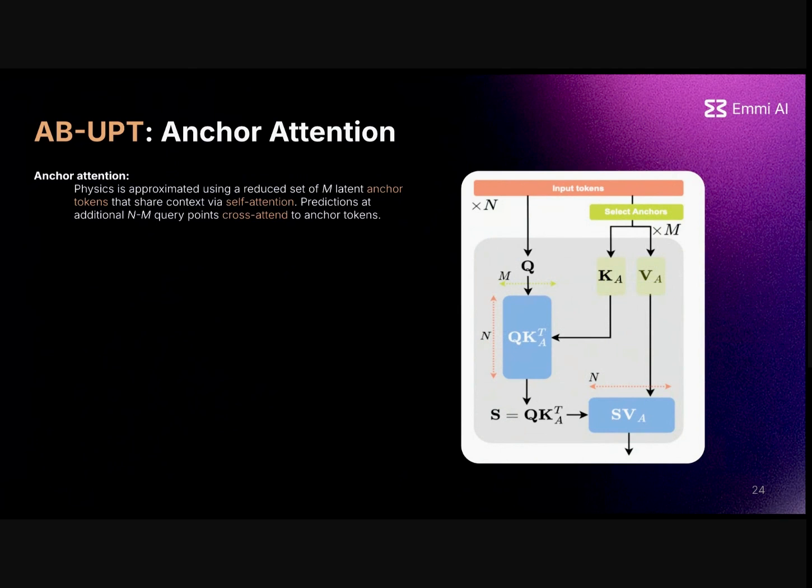But our model, as you just have seen, relies heavily on the transformer architecture and therefore on the self-attention block, which has a quadratic compute and memory complexity given the number of input points or input tokens. And if we want to scale to simulation-size meshes like DriveNet with hundreds of millions of input points, this complexity will explode and will be infeasible to compute.